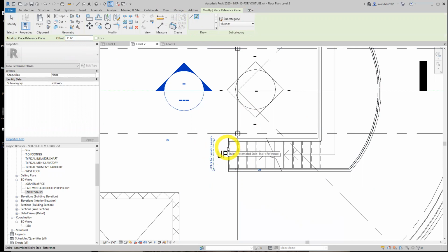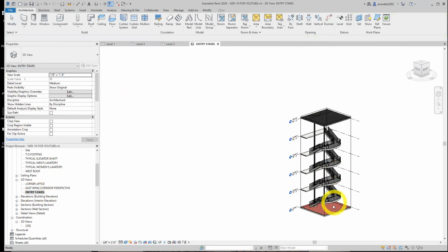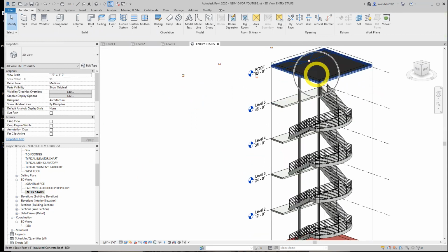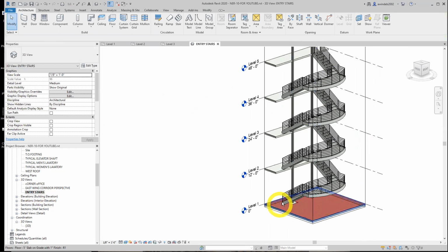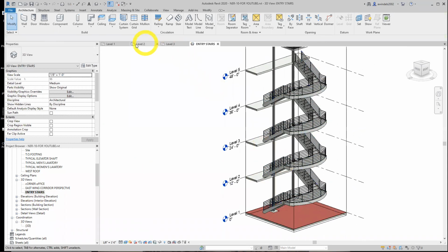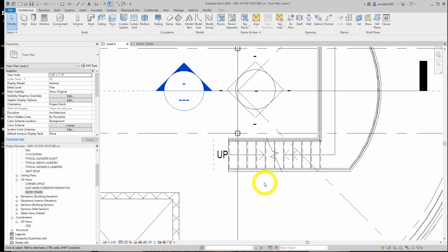And we're going to extend the railings. Keep in mind, we're on level 2. I accidentally did this in level 1 earlier. So think about it this way. Let's open our view back up for 3D. We're right here, creating it right here. We're making a railing here so people don't fall off. We're going to copy it up to here, here, in level 5. Here's the roof. I accidentally at times made it down here, which isn't a big deal, but we don't really need it down here in level 1. So easy to get lost between the levels on these. Just keep in mind. Let's even turn some of them off for now. We're on level 2.